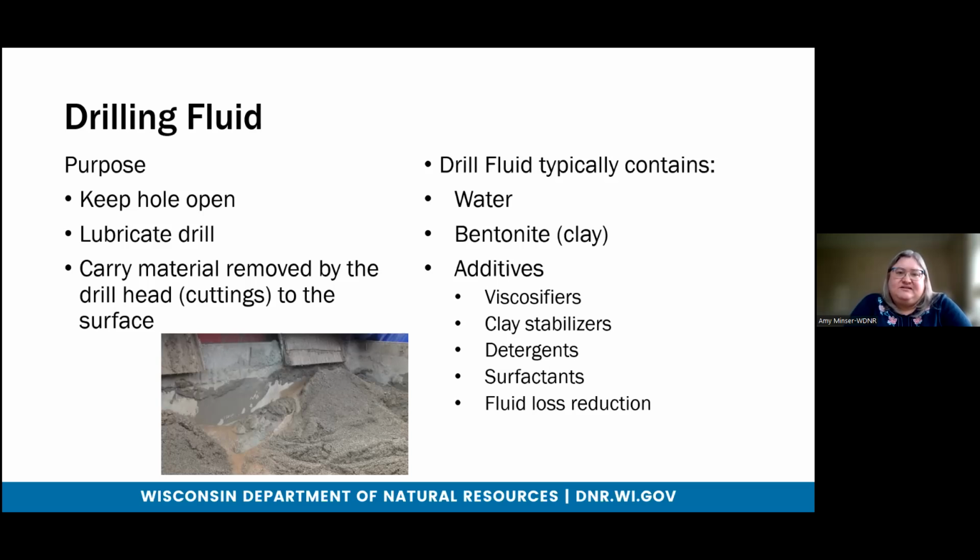And the drill fluid is usually over 90% water, and the bulk of the rest of it is bentonite, but there may be specific additives used to help the drilling fluid serve its purposes, and to also help keep the drilling fluid within the hole.